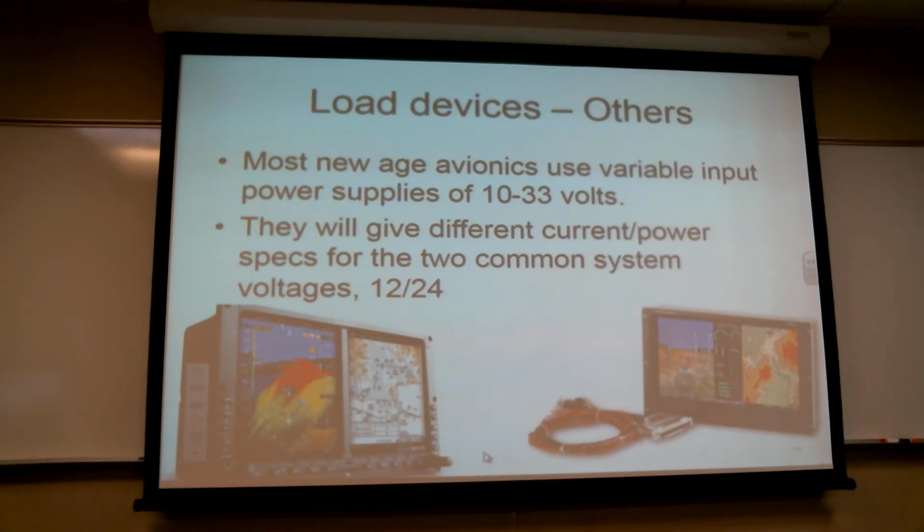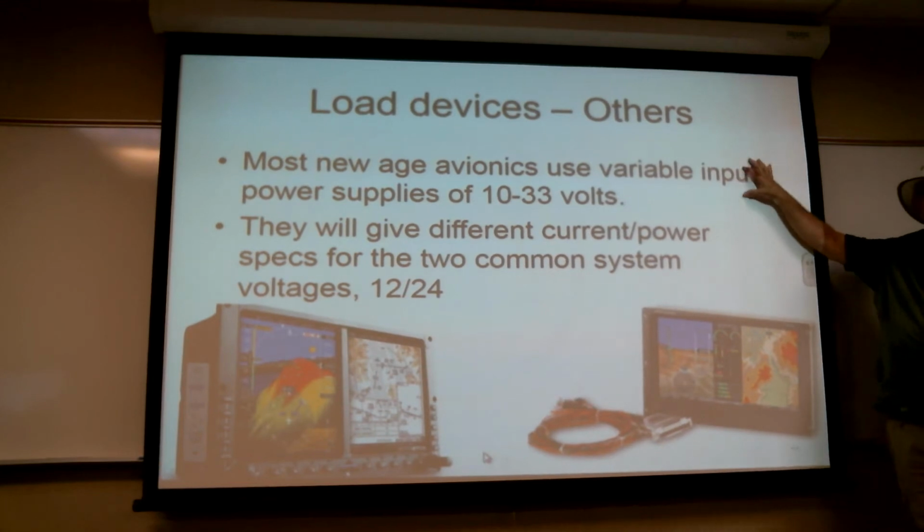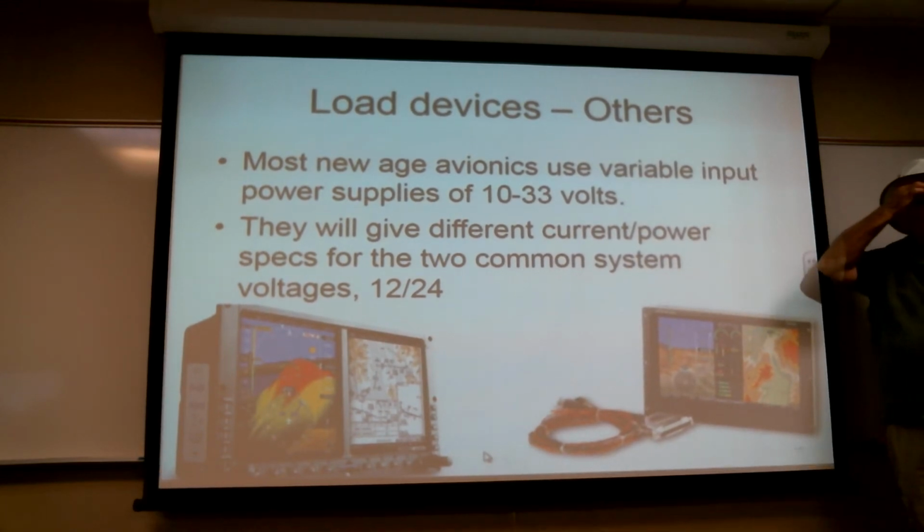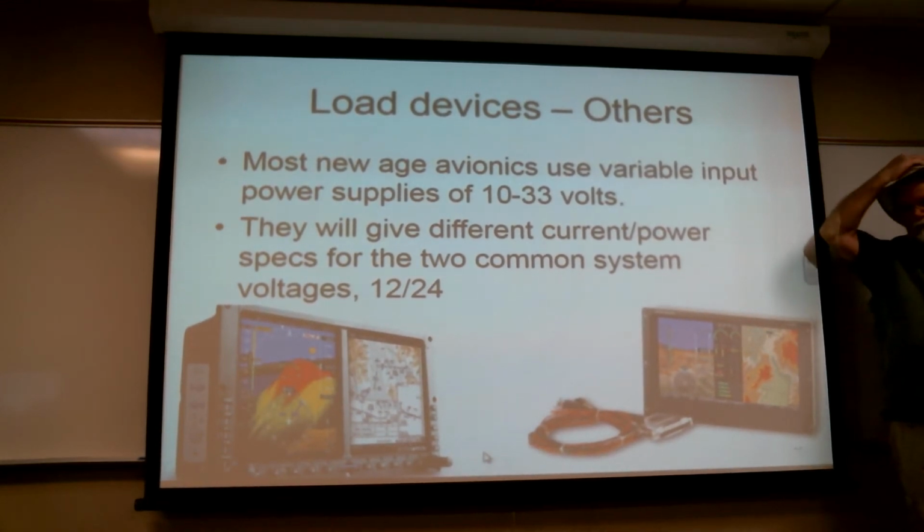Why did they do that? Well, probably because if it was in a 15-volt system or it was in a 30-volt system and somebody bumped it down to 15 volts and then it got turned on again, it would damage things. Well, it makes a whole lot more sense just to make a universal power supply that it doesn't matter what the voltage input is, up to 33 volts.